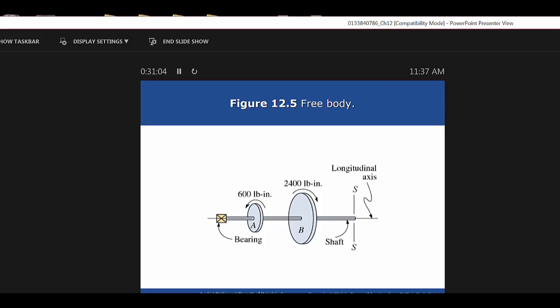You need varying speeds? You need different speeds coming off. As coming off the pulley, well, typically they are, because the diameter of the pulley is going to have different speeds coming off. But down at the axis though, what's the speed of any of them? Down at the axis of that shaft, the speed is 0. Just like the torque is going to be 0.